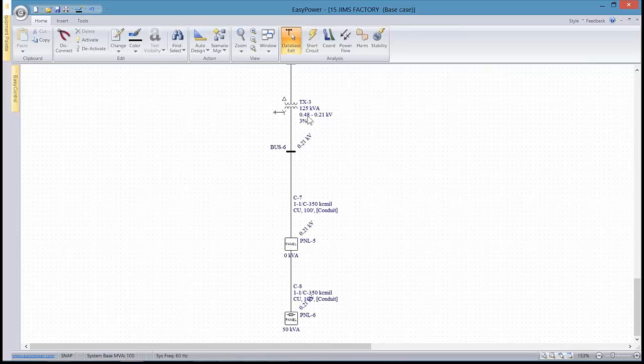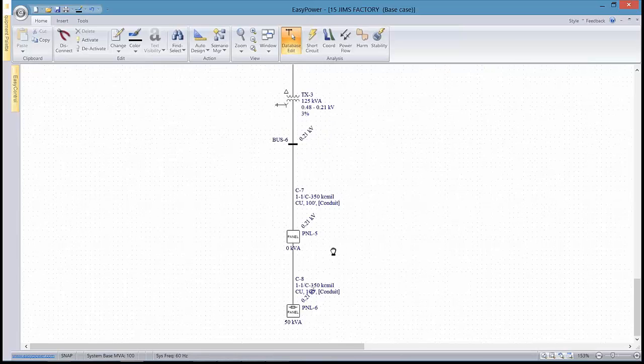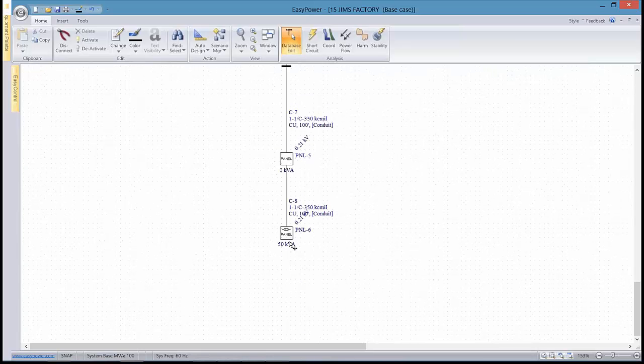In this case, we're talking about a lighting panel, so this is a step down 125 kVA. Again, IEEE indicates that this is kind of the crossover point at the level at which you expect relatively low risk of an arc flash hazard, but the tool still allows me to do calculations.